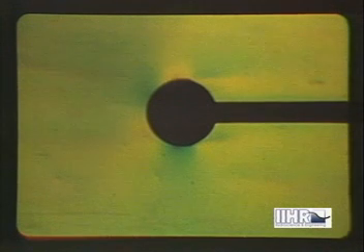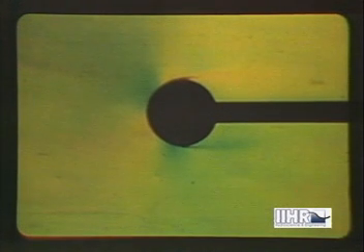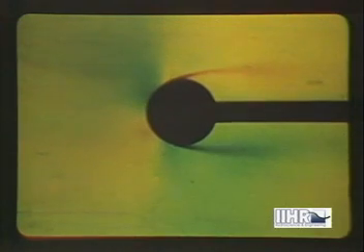As shown in these sequences made at the Aberdeen Proving Ground, the optical method known as Schlieren produces a diffraction of light that varies with the density or pressure of a flowing gas. Here, subcritical flow is developing past a sphere, the zone of positive pressure above the axis becoming green, and that of negative pressure red. Below the axis, the opposite is true.